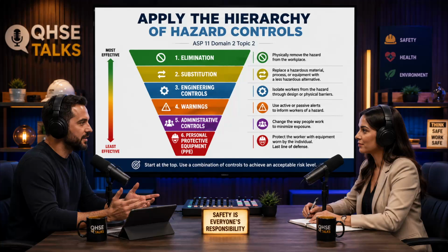That brings us to the operational reality of risk management, and a concept the industry calls prevention through design, or safety through design. This is where the hierarchy of controls is utilized at its maximum potential. Prevention through design is the strategy of integrating hazard analysis and risk assessment methods incredibly early in the life cycle of a project. You aren't walking onto a finished factory floor and trying to figure out how to put a guard on a dangerous machine.